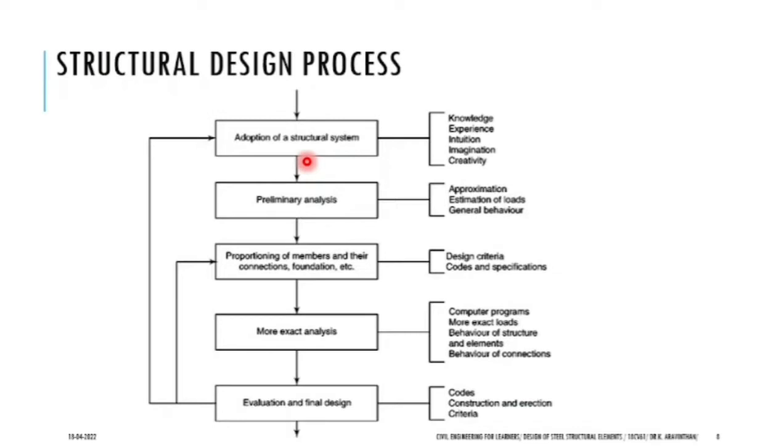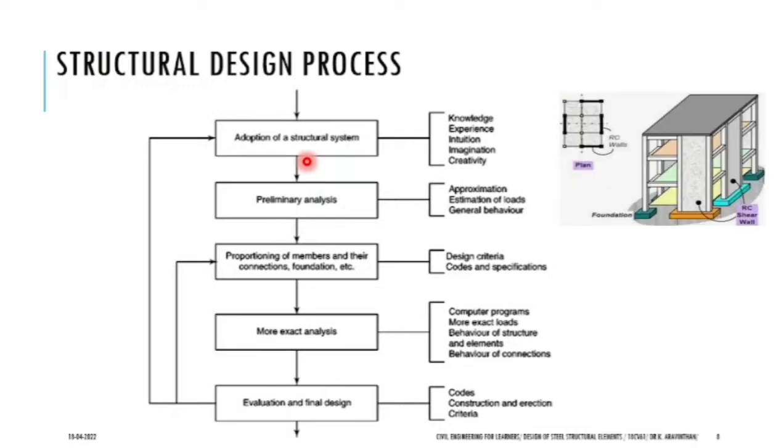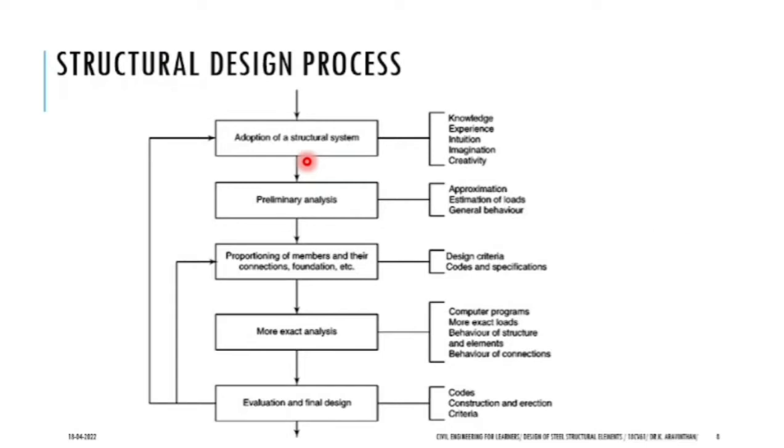But if you are going beyond 7-story or 8-story, only beam and column is not sufficient. You need an additional structural member, so shear walls are introduced there. If you are going for too much height, see, your classroom is a height of 4 meters from your floor to the roof. If this is the case, the frame is sufficient.